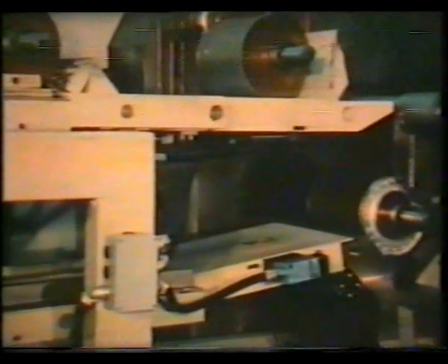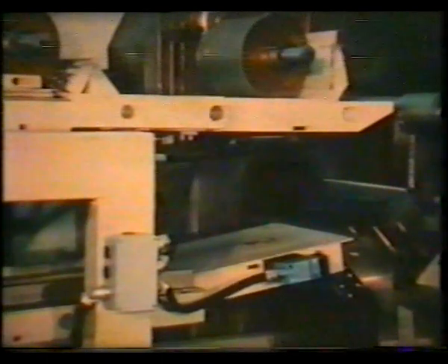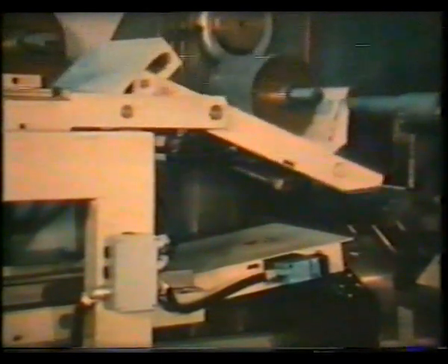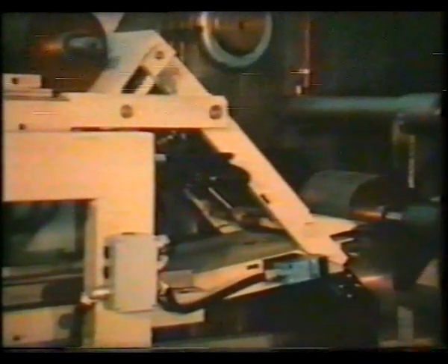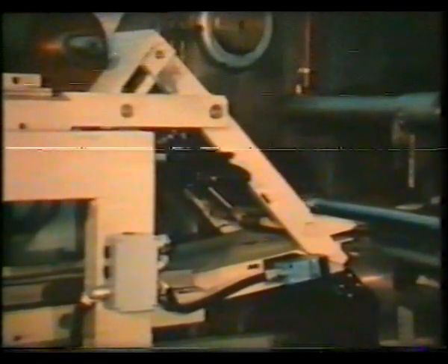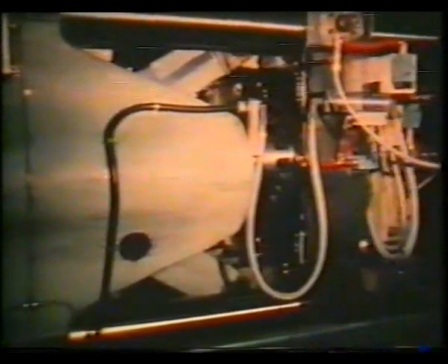The radial thrust motion causes the rotor to roll away on the inclined discharge ramp. A new cycle is initiated by loading a laminar stack into the die. The runner of the previously cast rotor is ejected. This facility is capable of turning out 40 rotors of the largest type every hour.